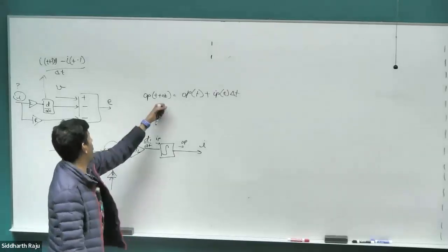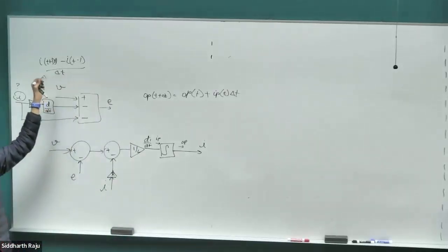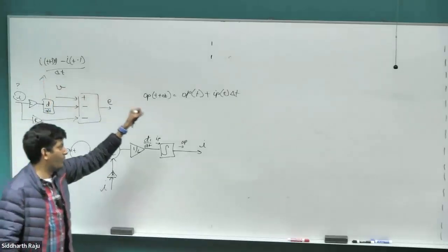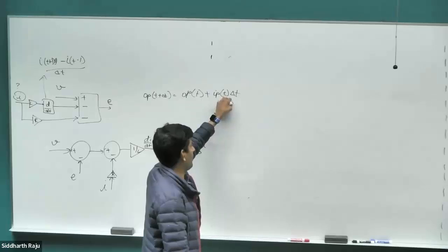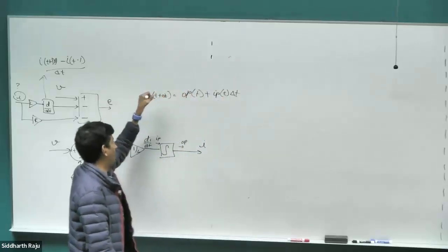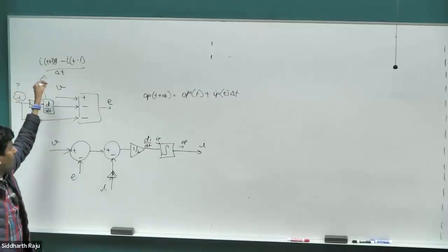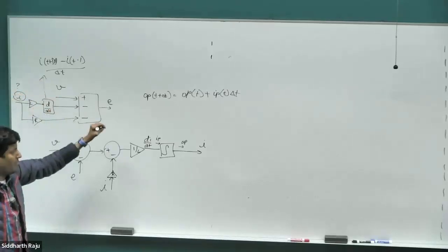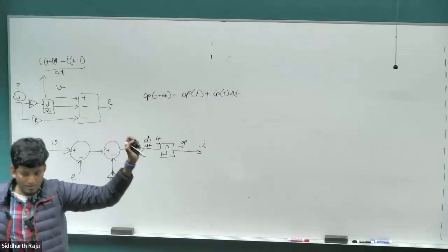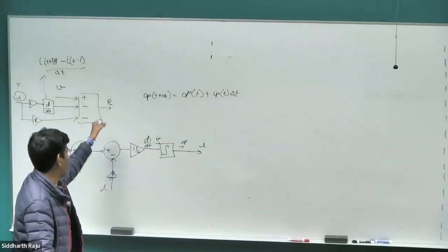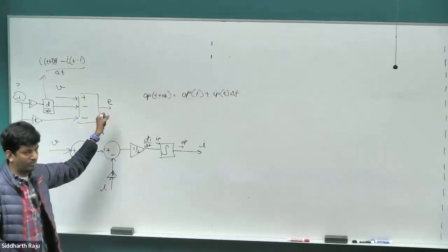Either of those operations is pretty straightforward. I prefer the integral operation because division is quite a complicated operation. Typically, you can do multiplication on a floating point processor in a cycle or two. Addition is a single cycle operation. Division typically takes about 14 cycles. So it's more expensive to do differentiation compared to integration in reality. But there is a much bigger problem. We want to avoid differentiation at all costs in numerical simulation.